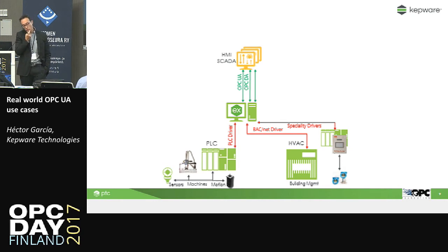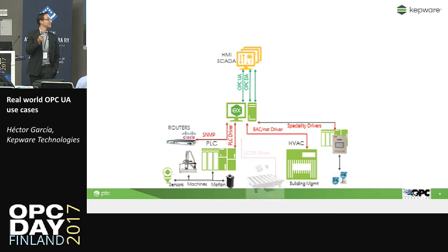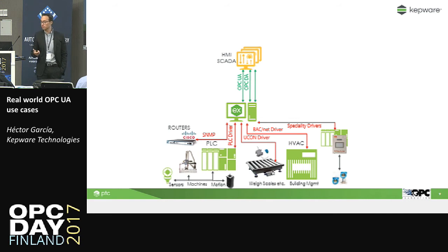We may also find some devices that don't implement standard protocols, like barcode readers or weight scales, but they implement very simple protocols of sending and receiving frames, and you can implement those protocols with a special driver that we call the UCON driver. It stands for User Configurable Driver. And as I told you, more than 150 different drivers, all of them using one single instance of Kepware X serving data to the SCADA systems in my plant.